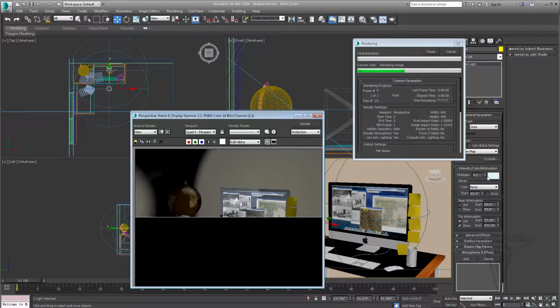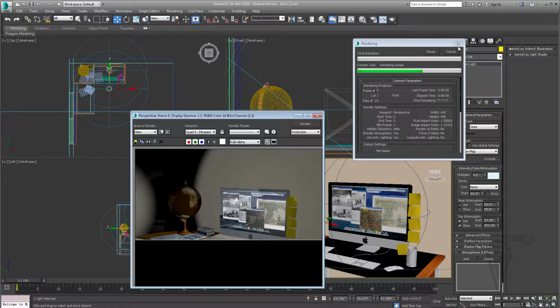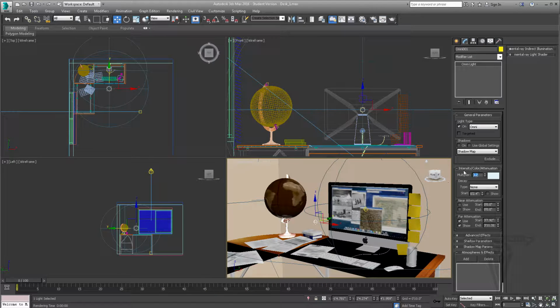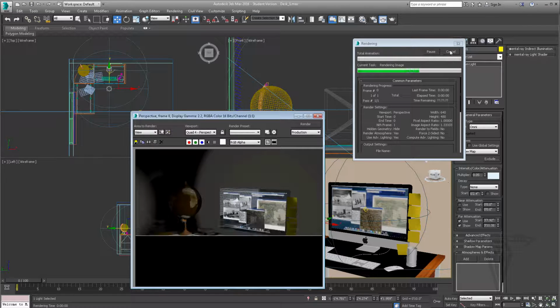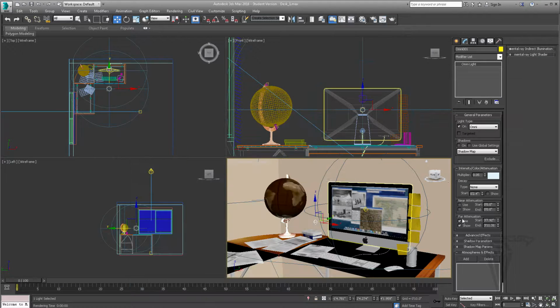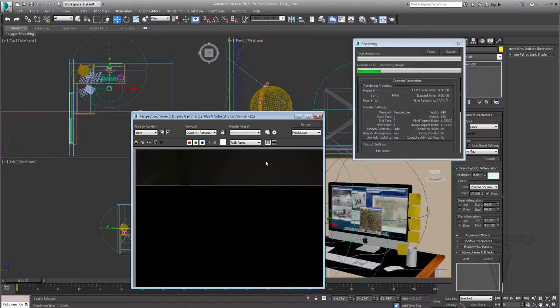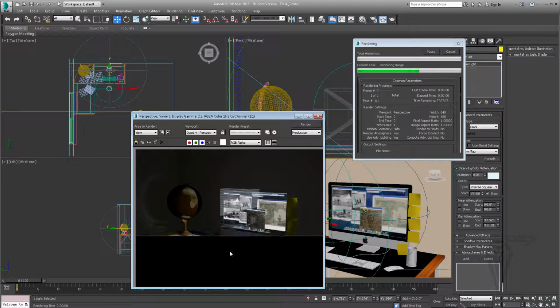And then obviously that's way too hot. 0.2 is way too much light. So let's decrease this to, let's say, 0.05. That's still way too hot. In fact, instead of using far and use, I'm going to use far attenuation. Let's go to inverse square, show, and let's start this probably somewhere around there. Let's see what that gives me. That's a little bit better. Actually, it's a lot better. So I'm giving the room a little bit more light.